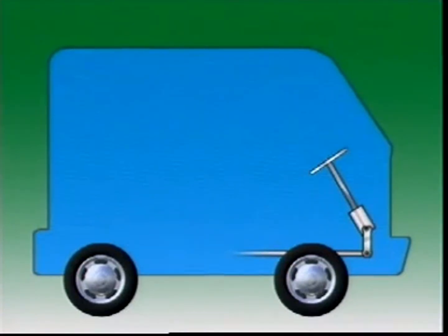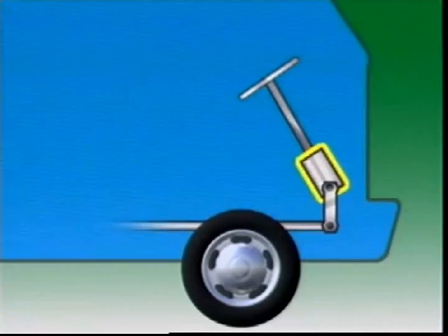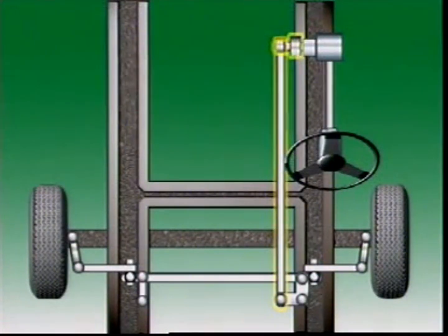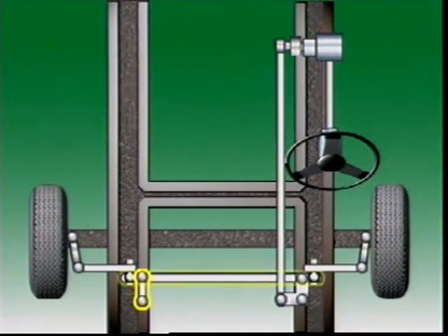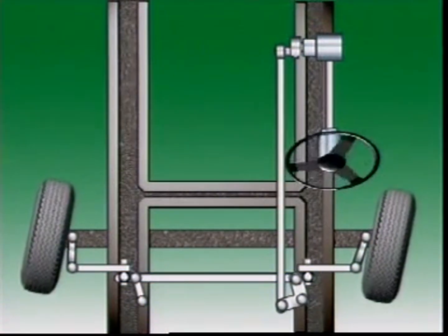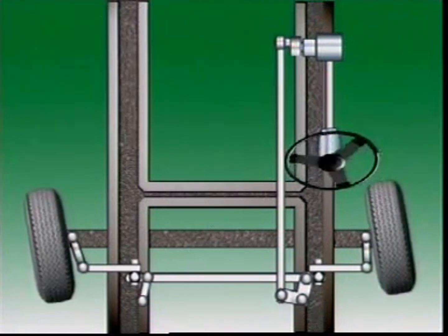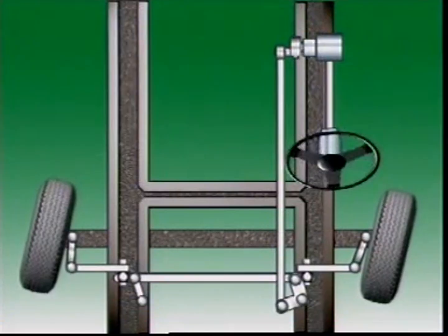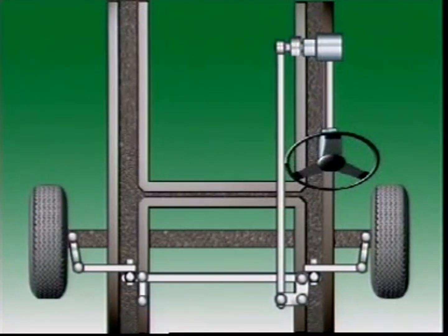In forward control vehicles, the steering system is mounted in front of the engine and wheels. The steering box is mounted on the subframe with the pitman arm vertical. A drag link transfers movement of the pitman arm to a relay lever which has two arms, one connected to the drag link and the other to the idler by the track rod. The longitudinal movement of the drag link pivots the relay lever.